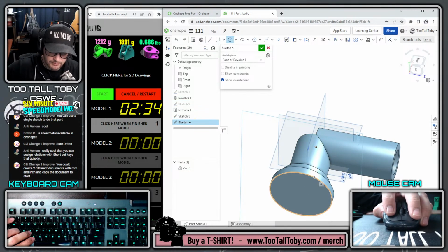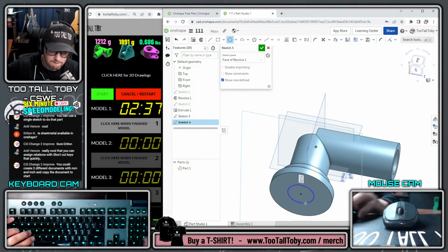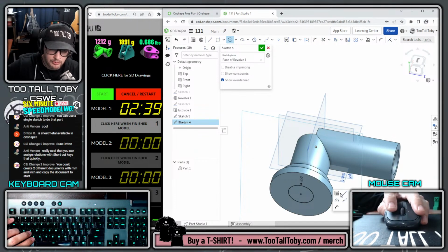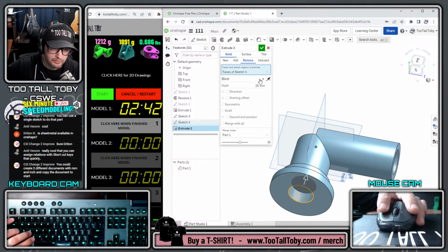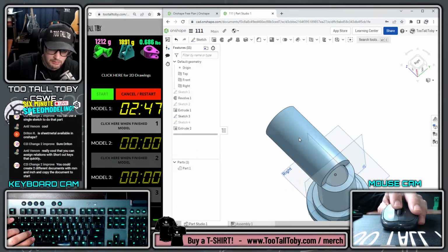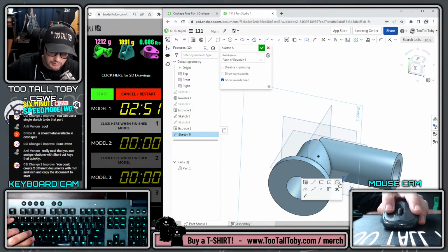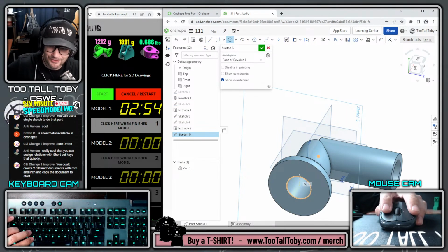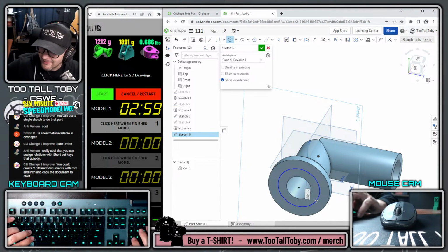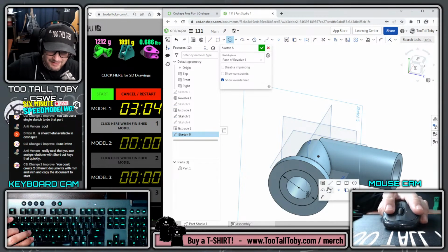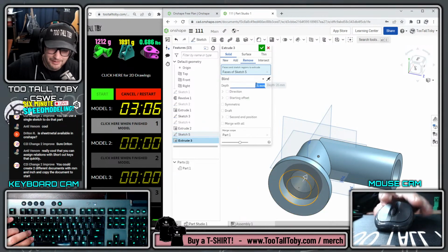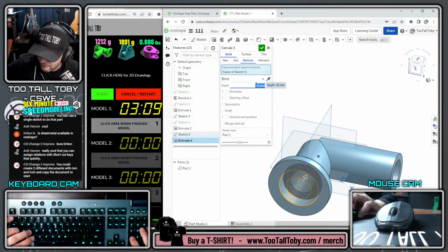this cut extrude at 50 and just go up to next, right? Just go up to next here. That should give us what we want. Yeah. And then we could do another circle here. This is very much like using the old school way of doing things, one circle per sketch. I think that's going to be a more efficient solution to this thing. So then this one's going to be at 80, and then that's going to get extrude cut to a depth of also 215.